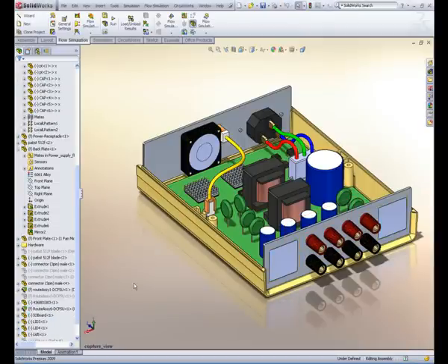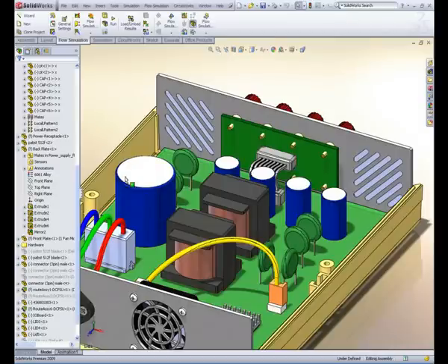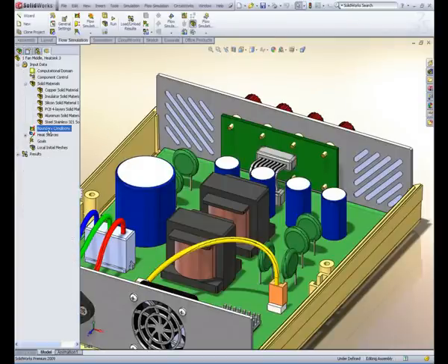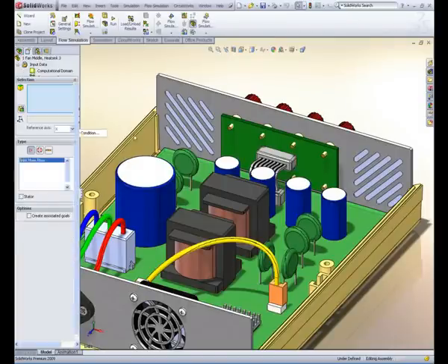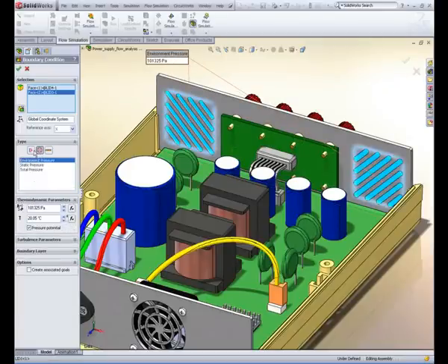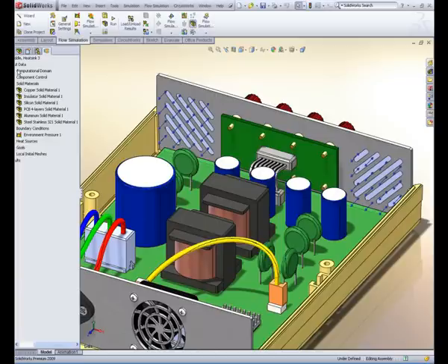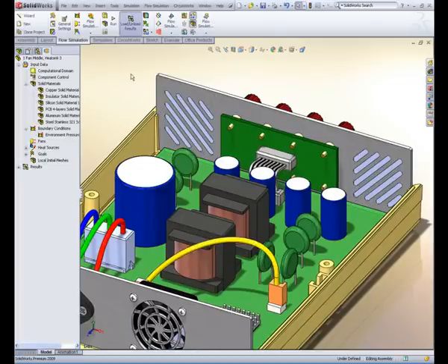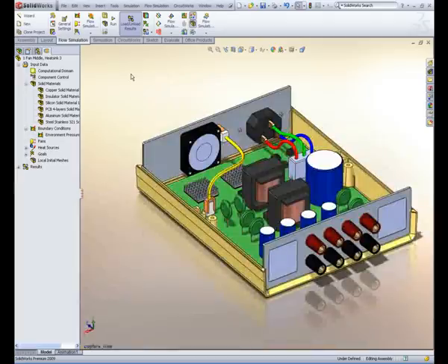So for example here we can apply normal environmental pressure to the two inlet vents, since these are assumed to be open to the normal ambient room. The same process of using a boundary face of a lid is used for the fan.